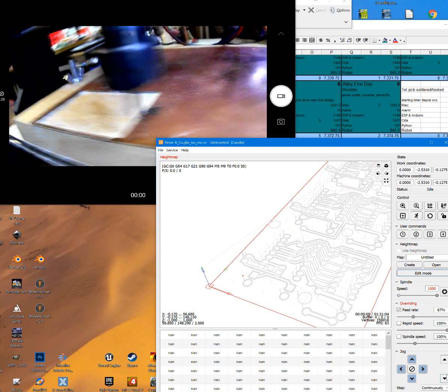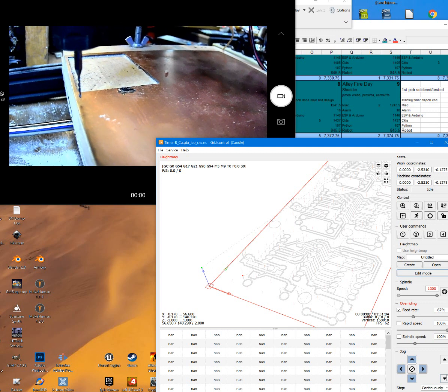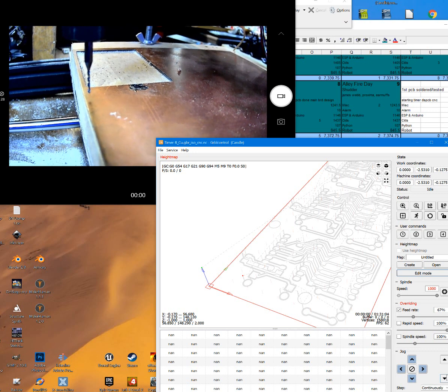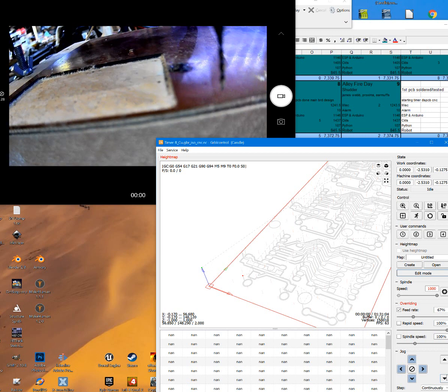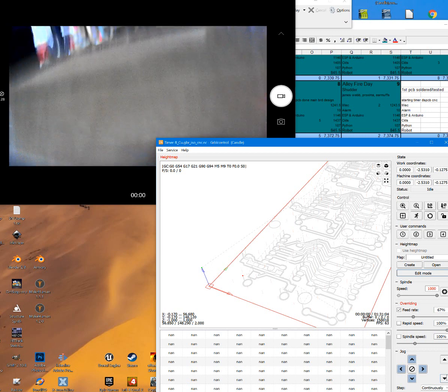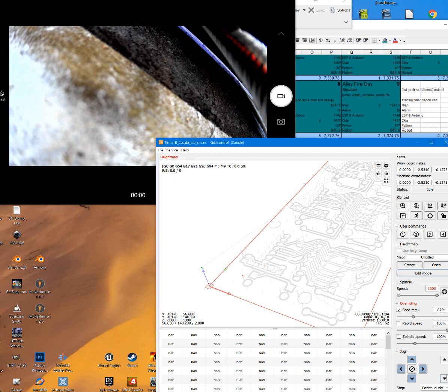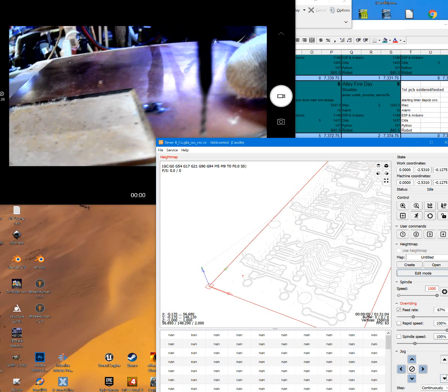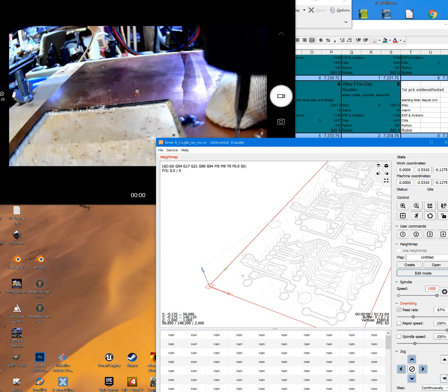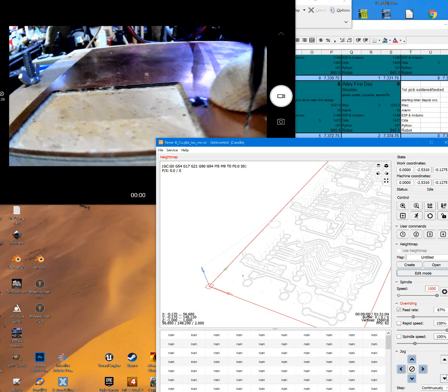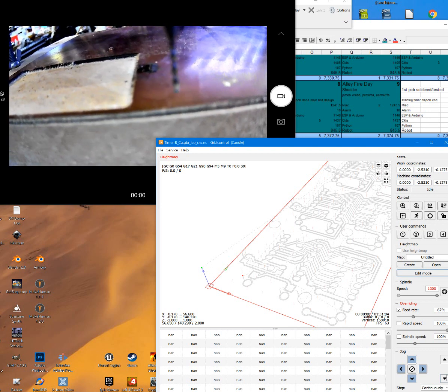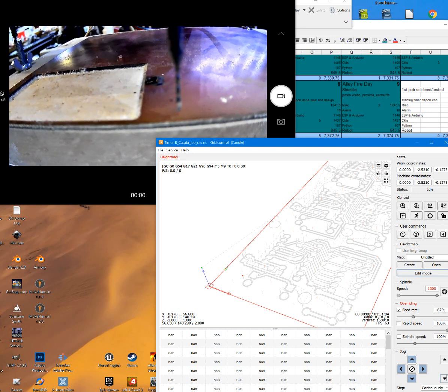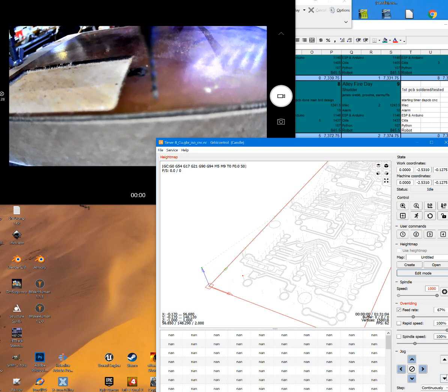That's good. Okay, I just try to get it to where, remember, our origin is inset, but I want to get it as close to this as I can. Hold on. Unfortunately, because I put that solder joint there, that's a bad place. I really don't want my tools to run into it, even though it probably wouldn't hurt them. Solder is such a soft metal, it can gum them up, so it's better not to route through solder if you can avoid it.